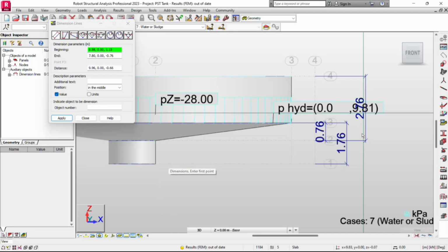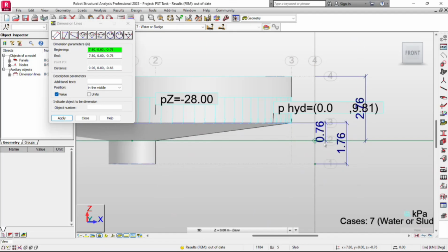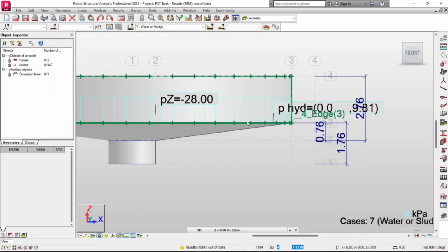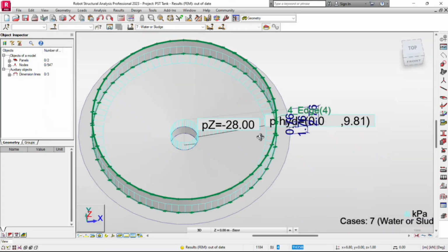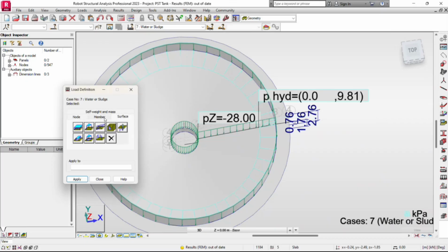So that's around 39.10. I'll just conservatively apply, it's usually 40 kilopascal, but I will conservatively apply 50 kilopascals, to be on the conservative side, 50 kilopascals pressure at the base.